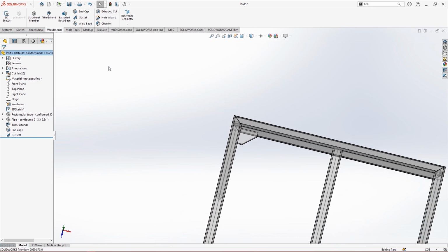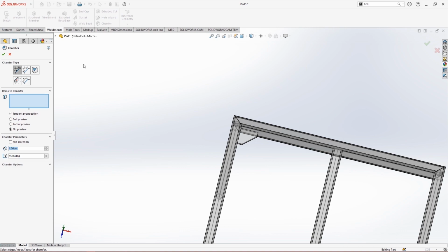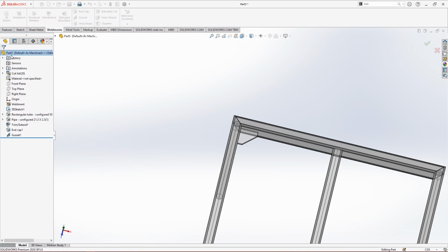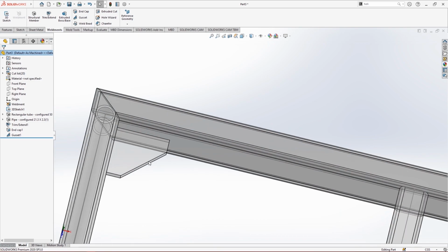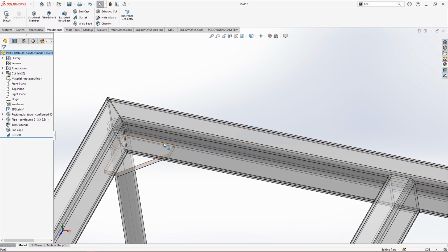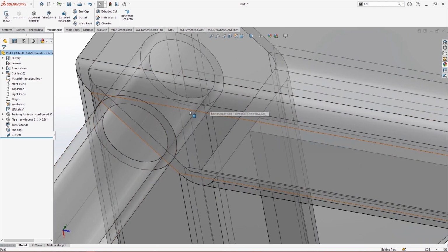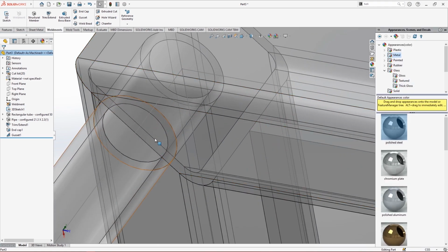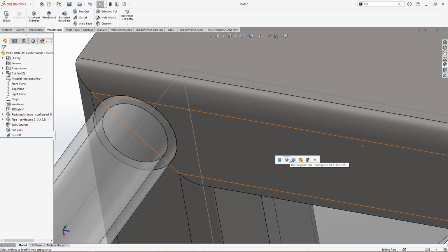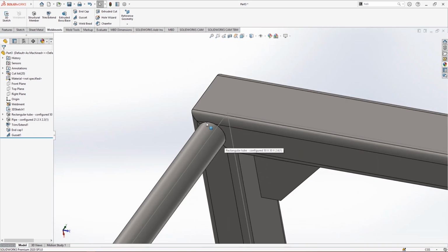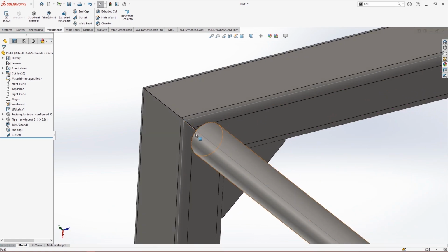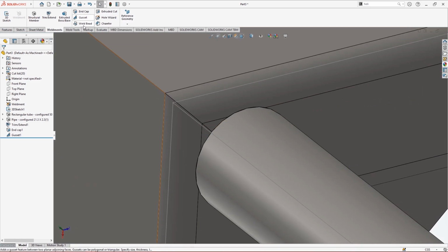Now what's left is a weld bead. There are two things in here, which is a weld bead, and another one is a chamfer. So let's just first check out the weld bead. If we want to represent that we are going to apply a weld along any structural member, we can present that using the weld bead. So let's just apply metal also here, so we have the whole structure in the same visualization. So let's just click on weld bead.